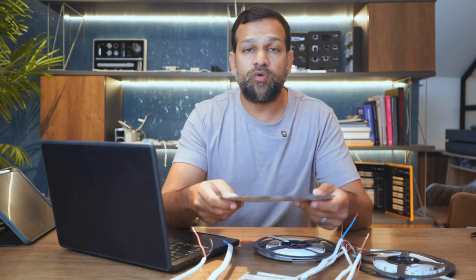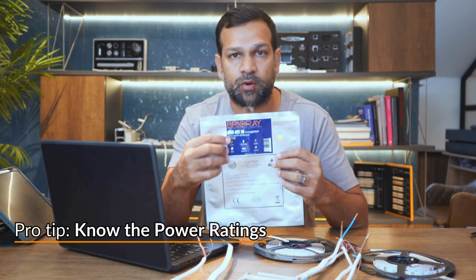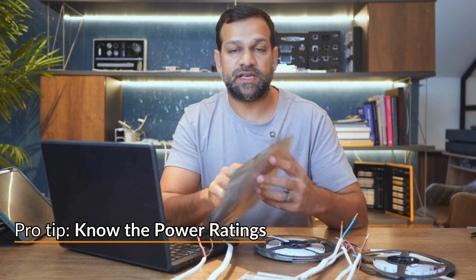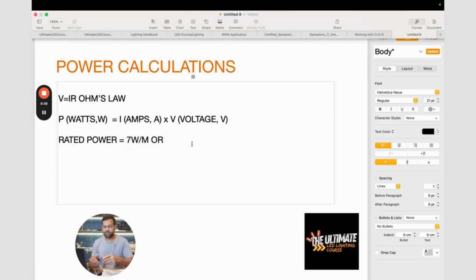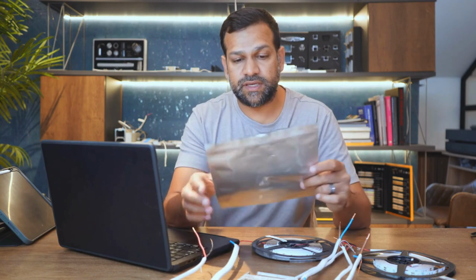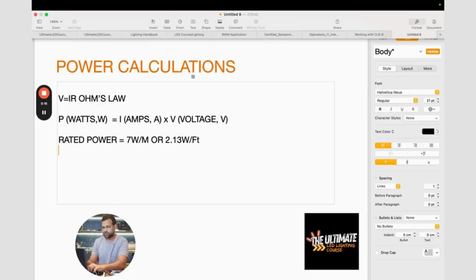The key thing, you always have to know the power ratings of your LED. And what you're going to see here is that this LED has power ratings on it that is 7 watts per meter. Let's write that down. So the rated power of this LED is 7 watts per meter, or 2.13 watts per foot. The other data input we're going to need is the voltage input, and you can see this is rated at 12 volts DC. So input voltage is equal to 12 volts DC.